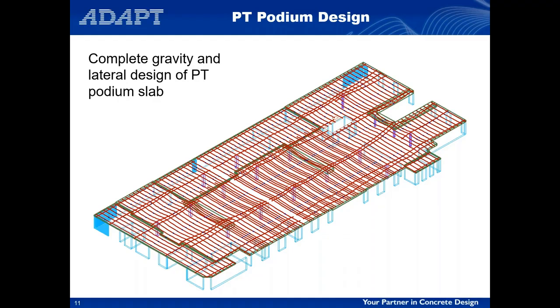One question does come up, and this just crossed my mind. It's not in the slides, but I do think it warrants raising this point. There's always the question of what boundary conditions you should consider. Keep in mind that when you're running the program in Floor Pro mode to design the actual podium, it defaults to a rigid roller, which means that the columns and walls below can develop a moment at the end, but they are not restrained in the XY horizontal plane.